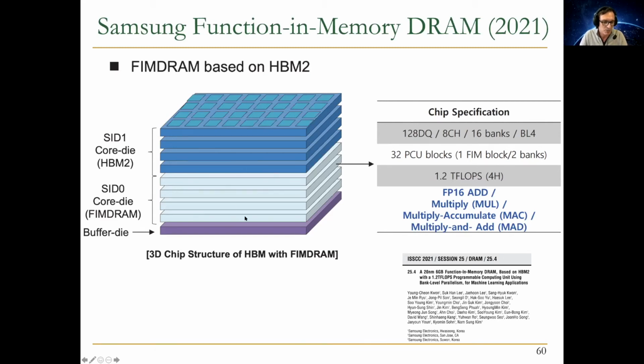But these compute processors inside the DRAM layer, inside the memory layers over here, can do floating point multiplication, accumulation, addition, and multiply and accumulate, which are heavily used by machine learning workloads. Clearly, you can use this for other workloads as well, that can benefit from this. But this is designed with machine learning in mind so that you can accelerate those workloads, because that's the workload that's really experiencing huge bottlenecks in terms of both energy and performance today.